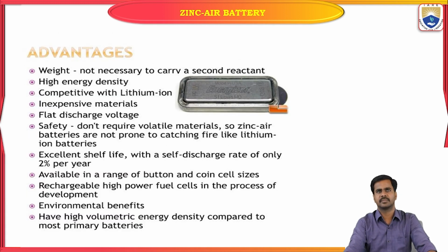Advantages. So, what are the advantages of zinc air battery? Weight: it is not necessary to carry a second reactant, and it has high energy density, competitive with a lithium ion battery. The cost of zinc air battery is very less, and it has a flat discharge voltage. Regarding safety, it doesn't require any volatile materials, so zinc air batteries are not prone to catching fire like lithium ion batteries.